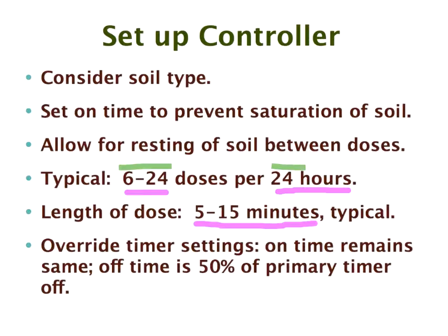And unless we do something, the alarm's going to go off. So to prevent that, if it's a comparatively minor problem, that timer, with the way we usually recommend this program, cuts the off time in half. So take that first example when I said we're running once every 3 hours for 15 minutes, then it will run every hour and a half for 15 minutes until that float drops.